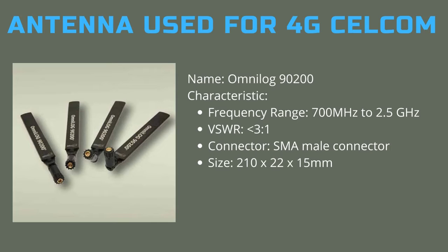The type of connector of this antenna is SMA male connector, and the size is 210 multiply 22 and 15. The VSWR and the return loss both measure the same parameter, which is the signal reflected back in a transmission line.